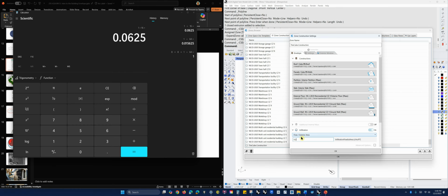So we're just focused on basically the insulation, the materials that are placed that will have heat flow through them, and then also air infiltration, air leakage, so we see how much air is circumventing that insulation and causing heat loss or heat gain. In this case, we're going to leave it at 0.2 CFM, cubic feet per minute. That's a volume of air per square foot of the exterior of our building. So this is just a measure of how tight we have made our building.